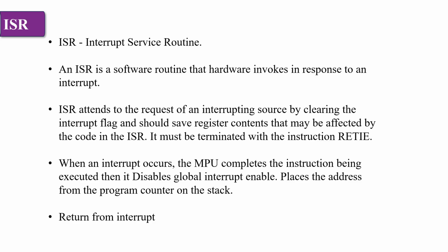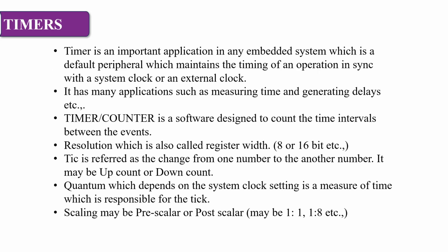When an interrupt occurs, the MPU completes the instruction being executed, then it disables global interrupt enables, places the address from the program counter on the stack, and returns from interrupt. Okay, next one is timers.